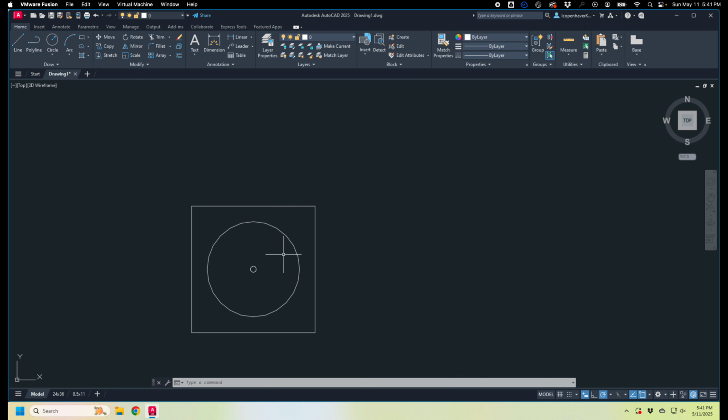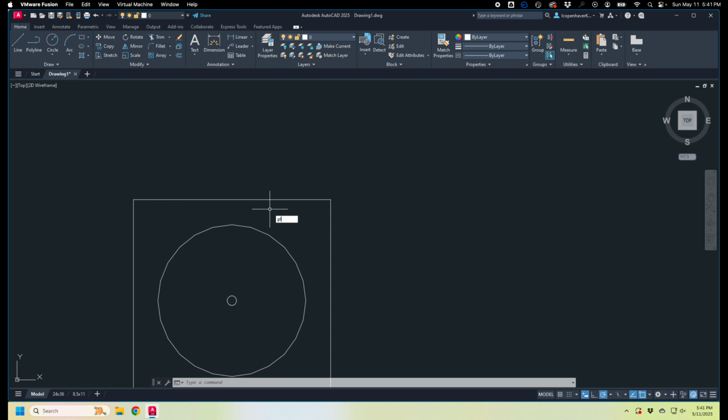So the first thing I want to do is cut off the corners here. Now, why do we do that practically speaking? That's so you can get your fingers in there when you're trying to run cable through a sheave. There's a couple of ways I could do it. I could just draw a line and place it where I think it should go. And then I could move this, maybe line it up to a particular location and then move it in a certain amount.